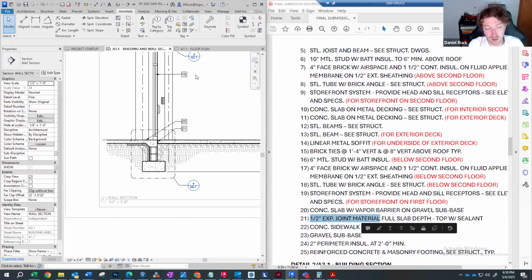That's because the bridge with the building was moving a lot more than the parking structure itself. So you have to allow additional room for movement, so that when that bridge does move, it's not pulling the structure away from the garage.